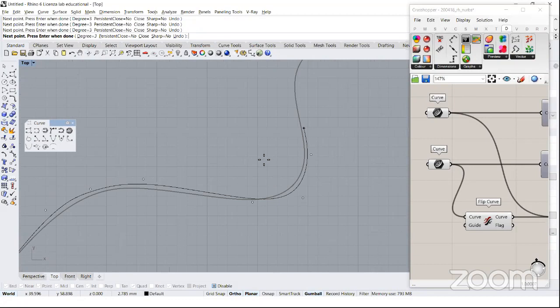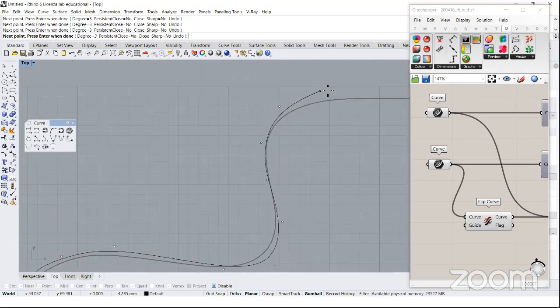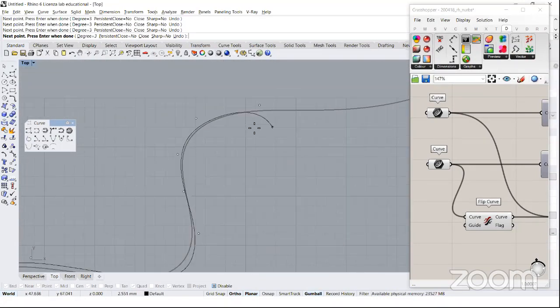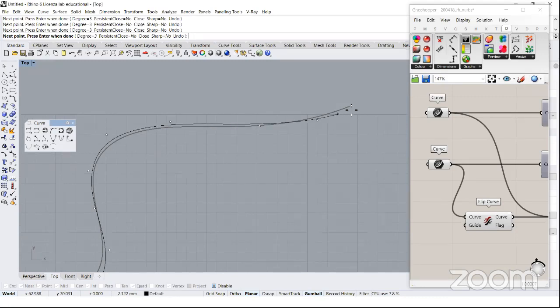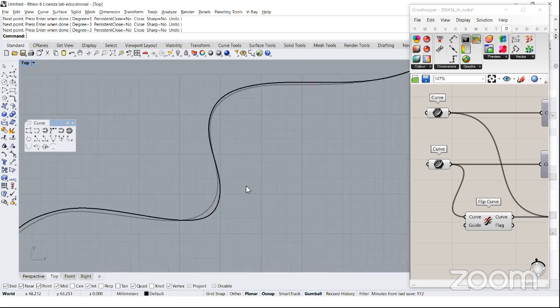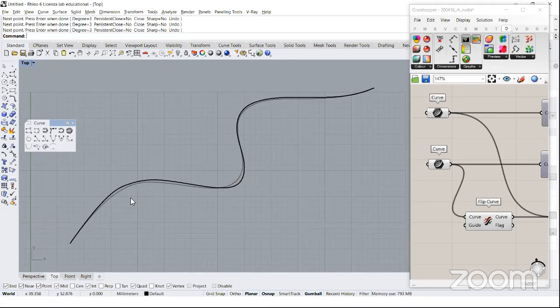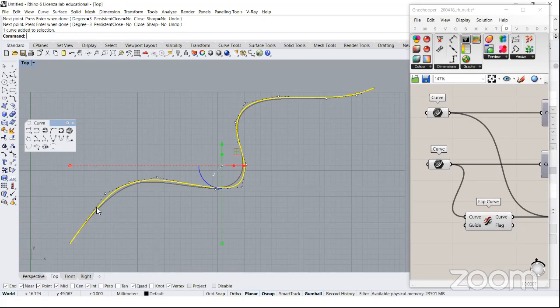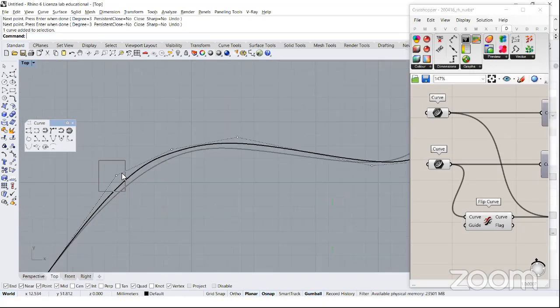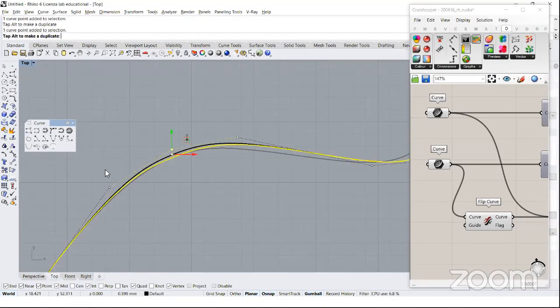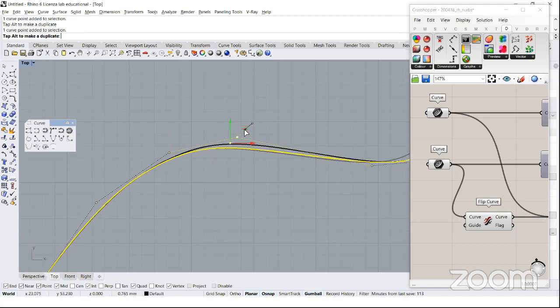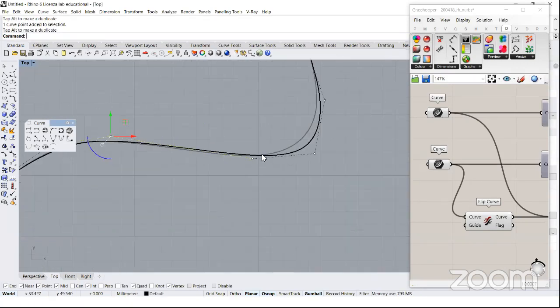And then this part is smoother, and another time we have more curvature, more control points, smoothness like this, and eventually the end point. Now, you see that this curve doesn't correspond to the original one, but its control points have a structure that allows better control over how precise I want to be when tracing this curve. This is something that you cannot do when you are working with an interpolated curve.